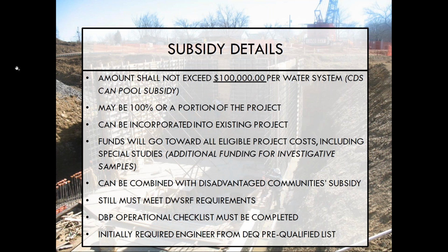If a system's already gotten started and just heard about the subsidy and wanted to use it, they could, but they have to be careful because you still have to meet DWSRF requirements, and depending how far you are along, it can be difficult to go back and meet some of those. Now, the funds will go toward all eligible project costs, including special studies. And special studies can include things like THM formation potential, hydraulic modeling, storage tank detention times, and also things like if you're wanting to do GAC, the rapid small scale column test, all kinds of things for special studies.